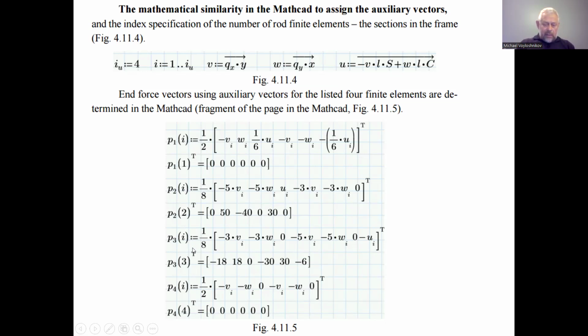And again, about the third type, this looks about the same as the element of the second type. The second type is embedded at the beginning and hingedly connected at the end. The third type is hingedly connected at the beginning and embedded at the end. We can see that the fourth, fifth, and sixth elements of the finite element of the second type correspond to the third type as first, second, and third elements.